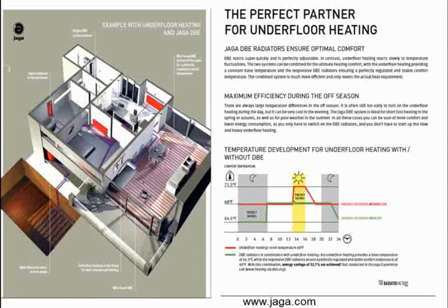All right, as we start talking about load side, what we want to do with the geosystem, and what you're going to notice here today is a lot of the things that we're talking about today are very similar to what we talked about in the solar presentations that we did. That being, we want to look for a distribution side or emitters that work at a low temperature, because the lower the temperature on the heating mode that we can operate the geo at, the more efficient it's going to be, the higher the COP.